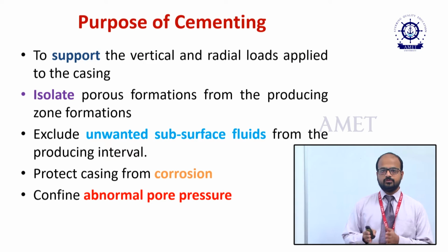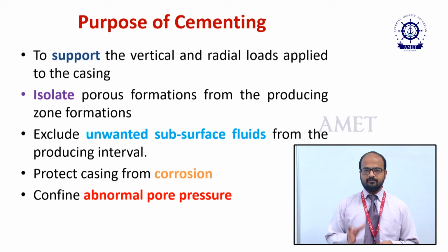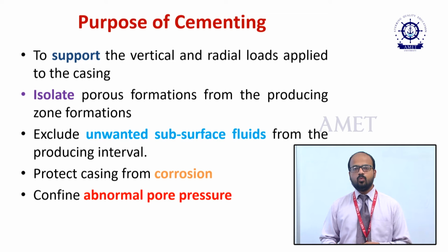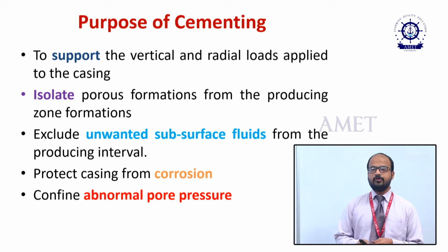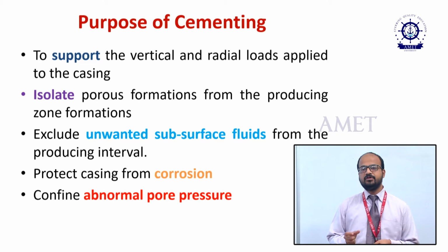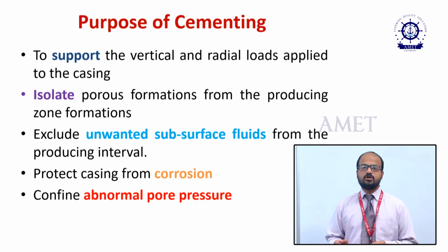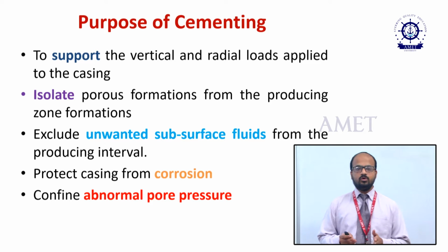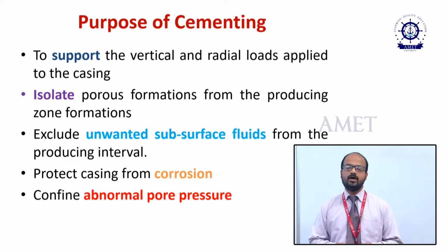Now, when we have to do the cementing, first we have to drill a well. It may be reaching some target or some depth. Once it is reached, then we have to insert the casing. If you leave it only with casing and not cemented, there will be a gap between the casing and the formation. Then what happens? Your casing starts to be shaken. If you want to control this shake, what do we have to do? We have to cement this annular space. So this job is called cementing.